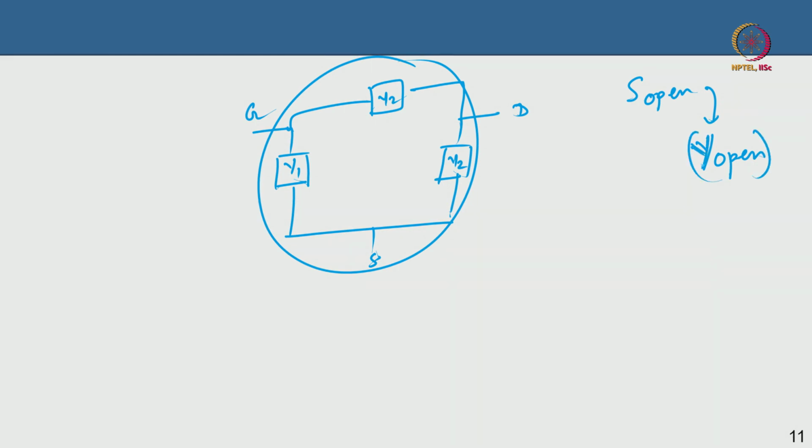You can always convert S parameter to Y, Y to Z, Z to H. You can convert from anything to anything. There is a lookup table. You can run a C++ or a Python script or something. Those equations are very standard. So you can convert the S parameter to Y parameter of the open, that is great.